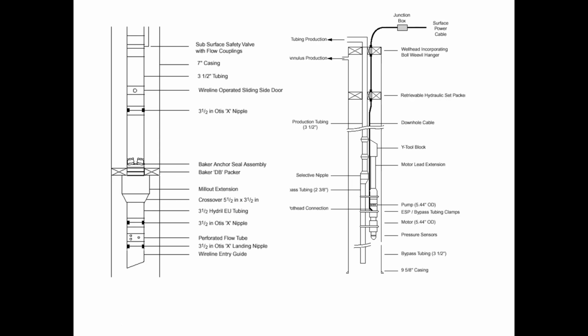Initially, we put in less power to prevent burning, because when you're just starting the pump it needs a lot of energy. And then you can increase the RPM and the power. Then the fluid comes to the tubing and goes to production, okay?